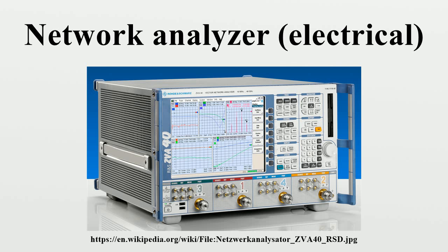Overview. Network analyzers are used mostly at high frequencies. Operating frequencies can range from 5 Hz to 1.05 THz. Special types of network analyzers can also cover lower frequency ranges down to 1 Hz. These network analyzers can be used, for example, for the stability analysis of open loops or for the measurement of audio and ultrasonic components. The two basic types of network analyzers are the scalar network analyzer, which measures amplitude properties only,